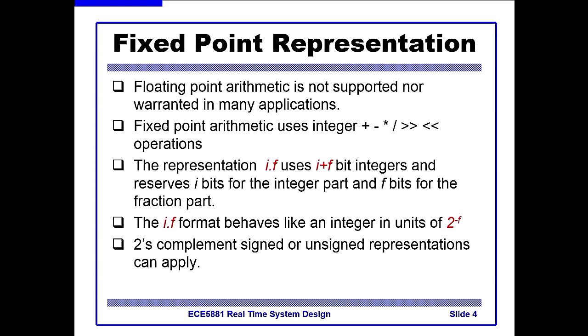All right, so floating point, yes, it exists, but in hardware it may not be supported by your processor, because it might be a low-end processor that, sure, it runs fast, but it doesn't have that extra cost of a floating point coprocessor. So if you were doing this in hardware directly, you can run fixed point arithmetic extremely fast compared to floating point. So there are big performance advantages.